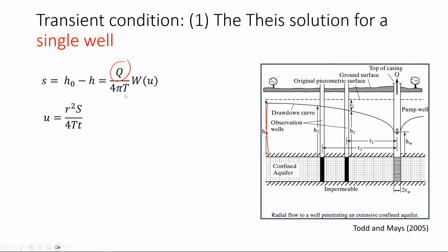That's what I want you to look at because in the next lesson we will learn about pumping tests. We have a whole series of lectures about pumping tests, but let me introduce it now and tell you why we do a pumping test. In a pumping test, we keep pumping the water and we keep observing drawdown. We start here, we pump, and after some time it's here, after some time it's here. So we keep observing this drawdown with time.